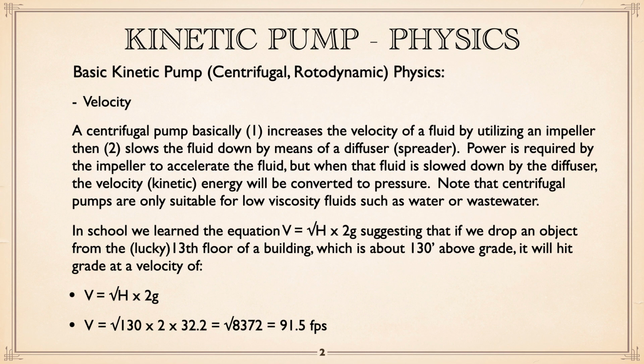You have an impeller, which is powered by a motor or engine, and its purpose is to increase the velocity of the fluid going through the pump. Now, as you add velocity to the fluid, you also are adding kinetic energy. And then, with that kinetic energy having been raised, when the fluid is slowed down, the kinetic energy will be converted to pressure. Note, by the way, centrifugal pumps are only suitable for low viscosity fluids such as water or wastewater.